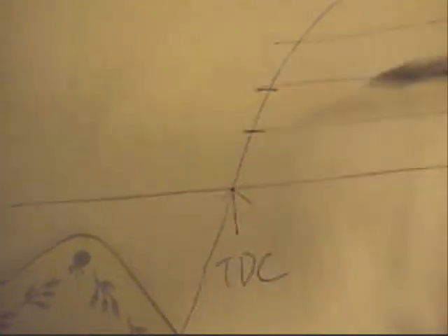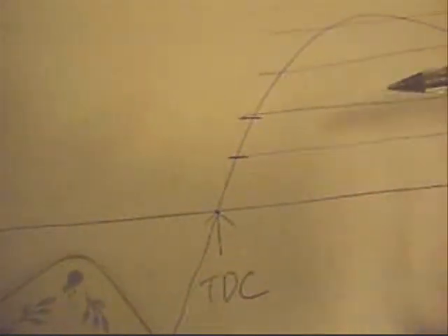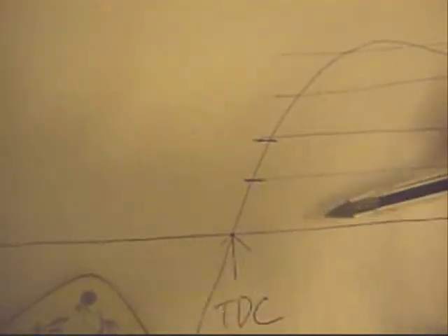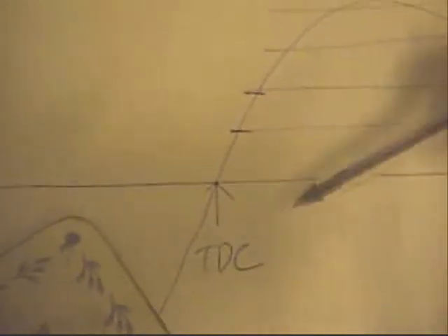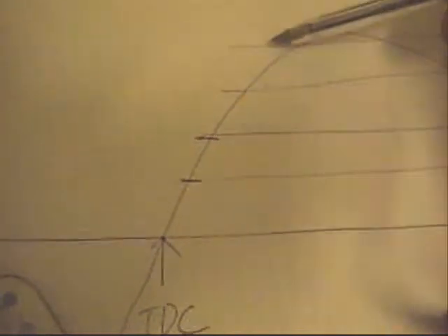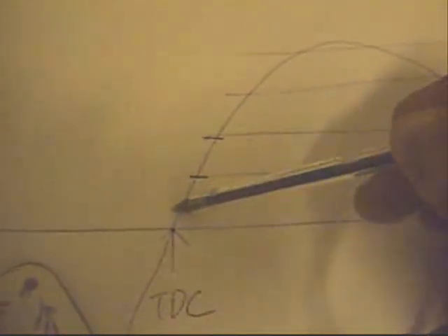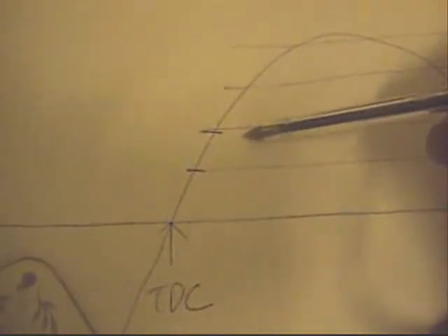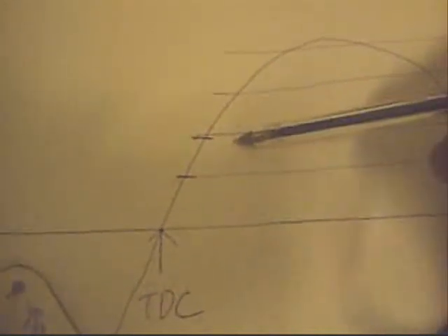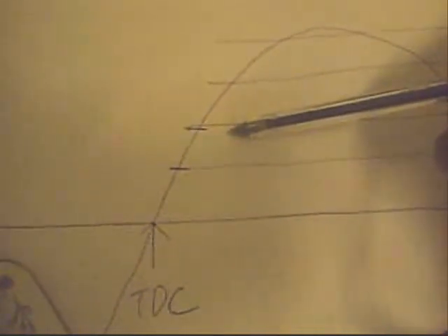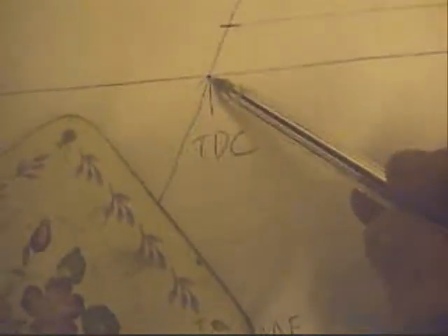Now, as you tune the pot to make it run faster, which is the odd thing, you move up this scale before it triggers. So of course, as you're increasing the resistance of the pot, you're actually delaying the trigger point, so you end up moving through time.